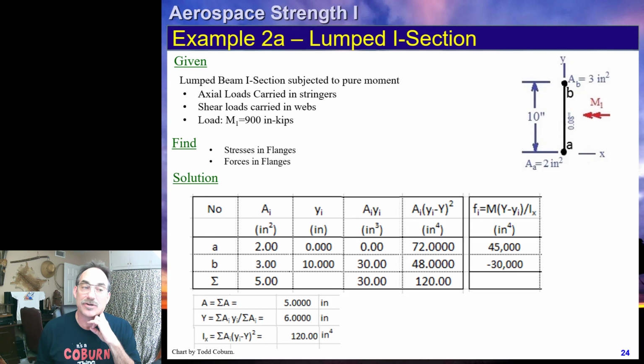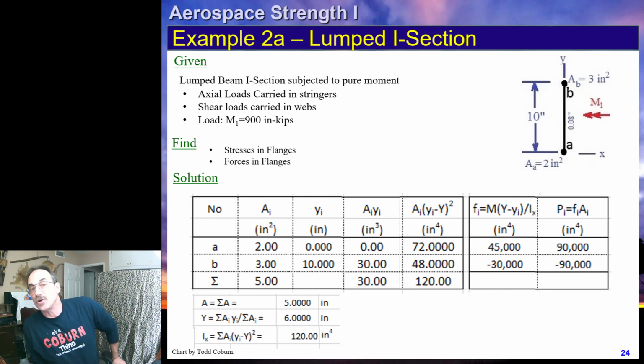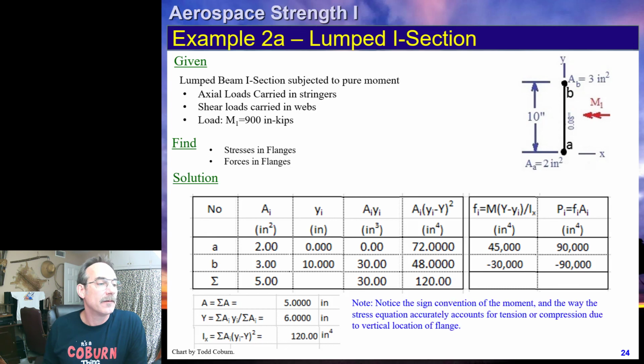And then we calculate our stresses. And if we wanted to, because this is a lumped section, it's very easy to now turn those stresses into forces by just multiplying each stress by its corresponding area.